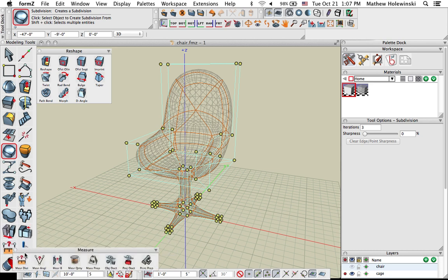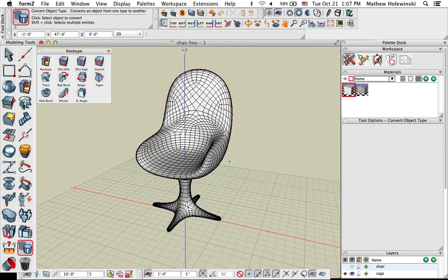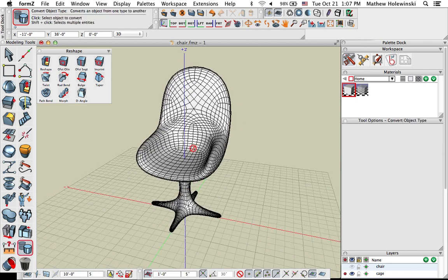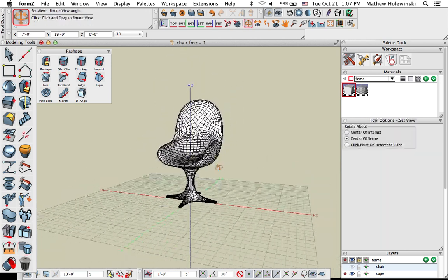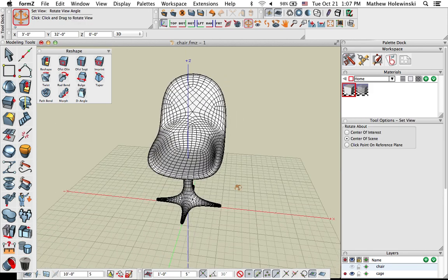So you're going to want to set the iterations first, and then if I were to select that thing and say I want this to be a plane faceted object, you can see now that the quad mesh resolution is set prior to converting that. Okay, and there we go. That thing's ready for 3D printing. So export that out to an STL file. All right.